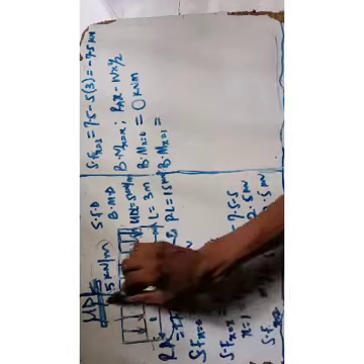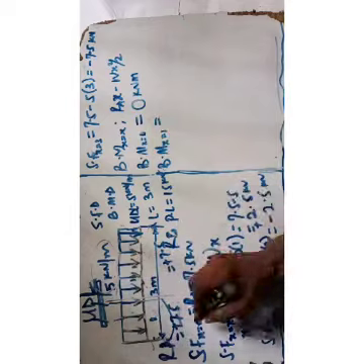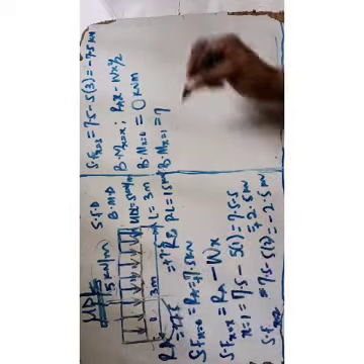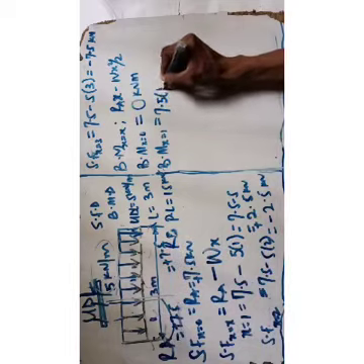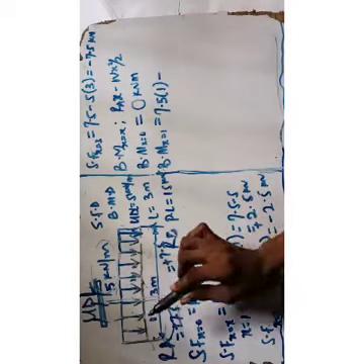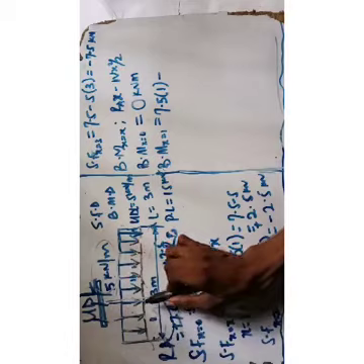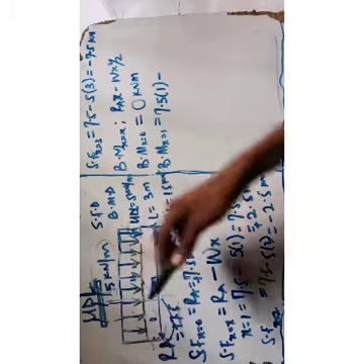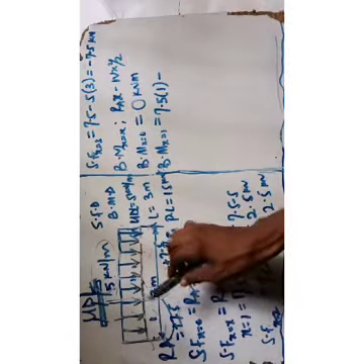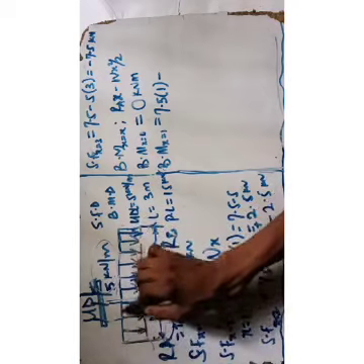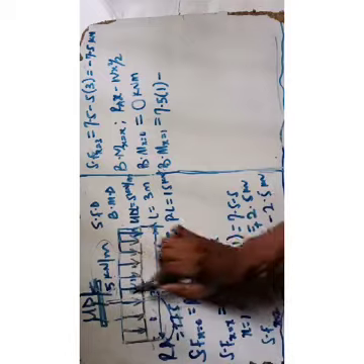Now bending moment when x equal to 1, here it will be what? When x equals to 1, that will be RA times 1, right? That will be 7.5. Take moments like this, that will be 7.5 times 1 minus, that is clockwise minus anticlockwise, 7.5 times 1 minus 5 times the length of this short one you are cross-sectioning. That is, this 5 you see the one acting here, it is distributed, okay.